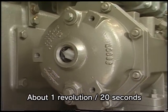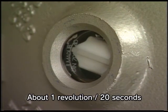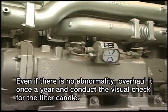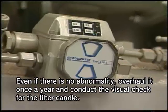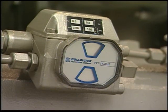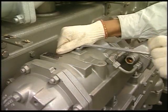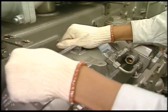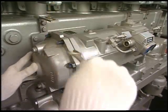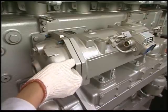At daily work, check both indicators of revolution and differential pressure while the engine is running. If the red portion appears on the indicator of differential pressure, disassemble the lube oil strainer to check and clean. Remove the air vent plug and drain fluid inside the filter. Detach the cover after draining.